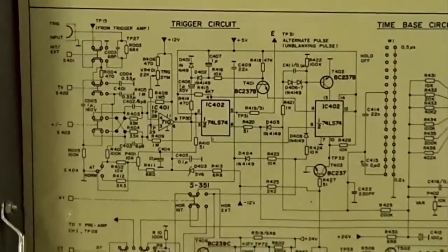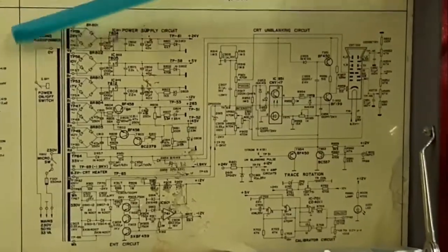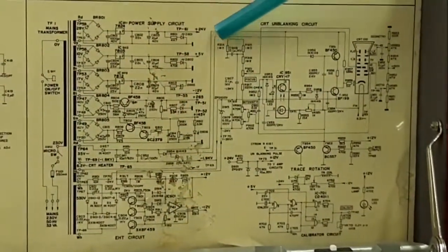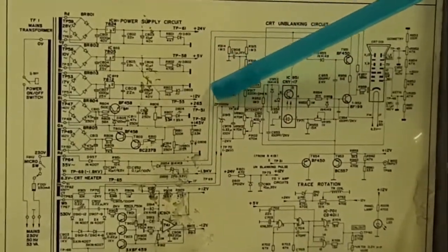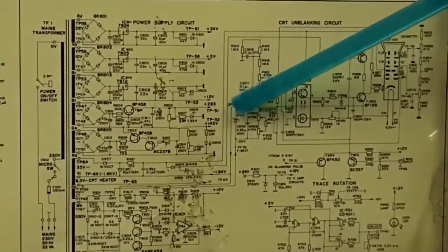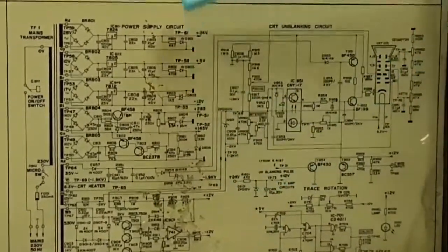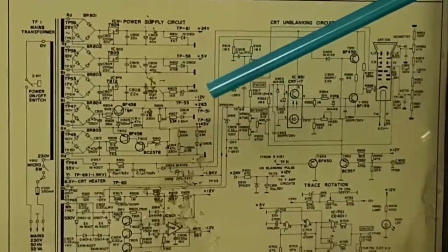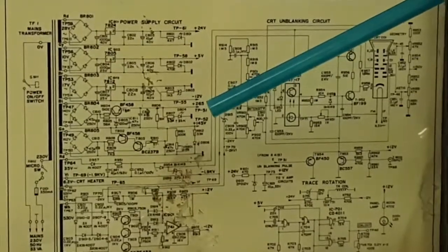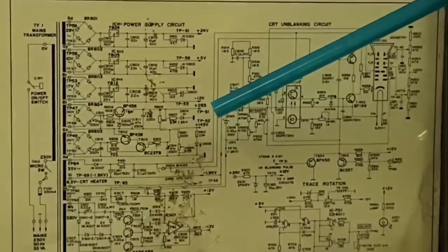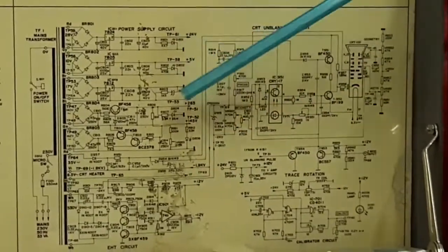Now, if you look at the power section here, we are observing so many types of voltages. For example, one may be 24 volt, another may be 5 volt, one may be minus 12 volt, one may be 265 volt, or one may be 145 volt. So the question is, why are so many types of voltages required here? Because the different sections of the CRO, like the vertical amplifier, horizontal amplifier, Schmitt trigger, trigger circuitry, and time-based generator, require different amounts of voltage, and that's why various power supplies are used here in the CRO.